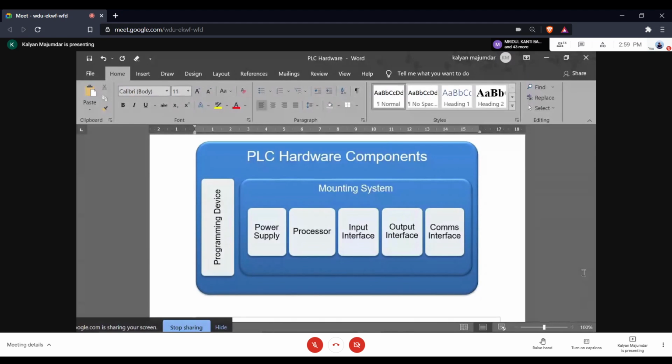The PLC is continuously monitoring the health of the entire system, of the entire hardware. And in case there is any malfunction anywhere, that is immediately communicated to your programmer. On your programmer, you can immediately see that some particular piece of hardware is malfunctioning. So what you could do is simply replace that particular piece of hardware. I'll come to this concept later, because PLCs are made in such a way that the replacement of hardware becomes very easy. That's not the case with your laptop, that's not the case with a desktop computer or most of the hardware that you have. But a PLC is specifically designed so that if one piece of hardware malfunctions, it becomes very easy to replace that particular hardware within a very short amount of time.